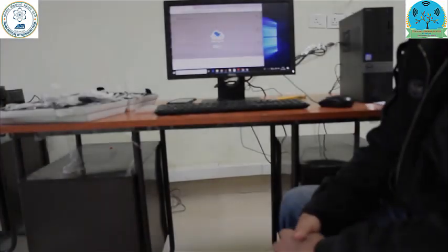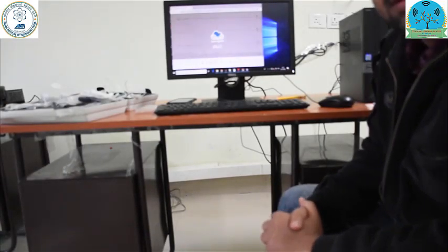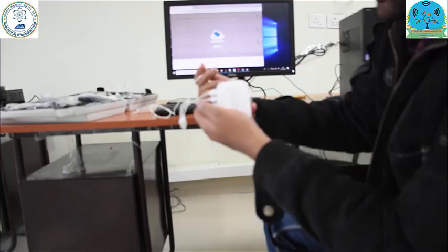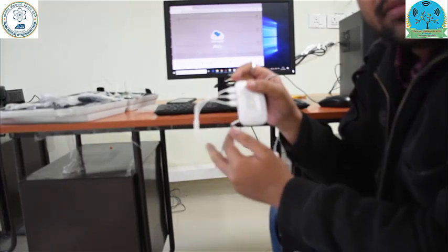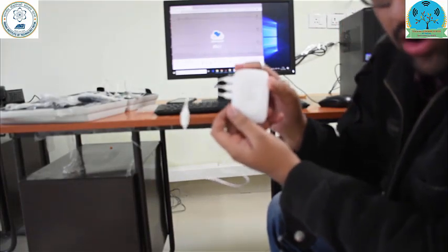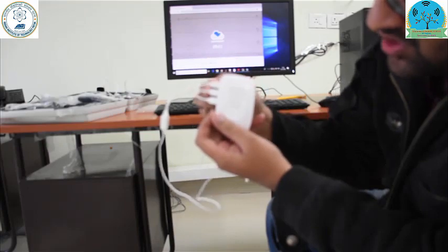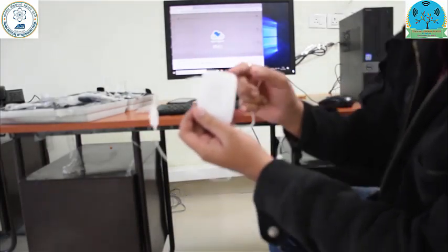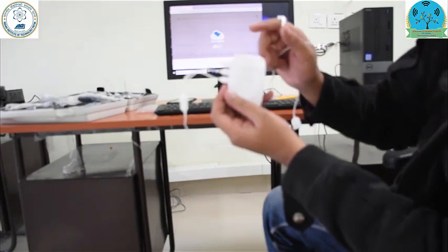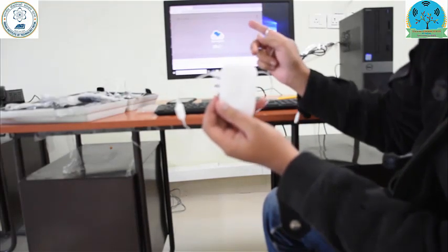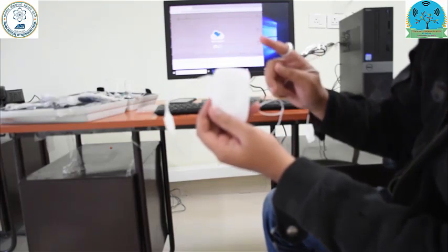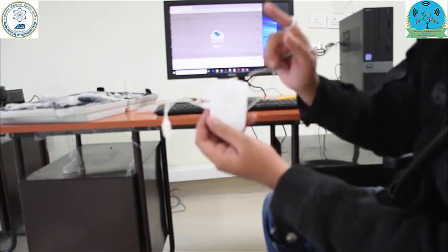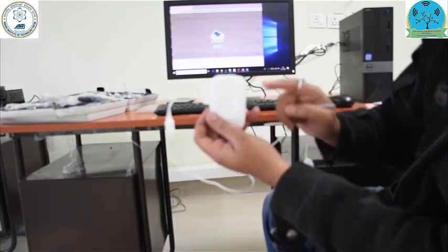So moving ahead with another sensor that I described before is the accelerometer. It measures the acceleration in the 3 axes, that is X, Y and Z. So this is an accelerometer sensor, and since we have 3 axes, I have deployed it on channel 1, channel 2 and channel 3. Now to enable this, I have to enable the 3 channels on my software also, that is the OpenSignal software, and then only the communication will be set up between the microcontroller and the device using the Bluetooth.